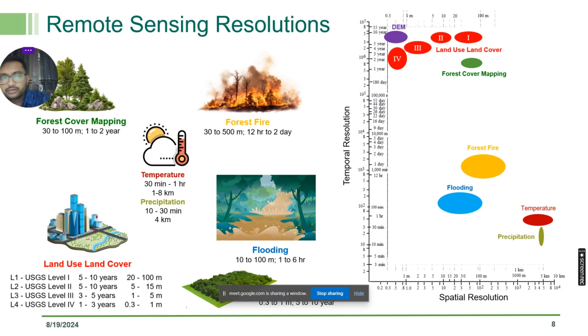Okay, so temperature is a property. We will not get it from the reflectance. When we talk about reflectance, the energy goes to the object, it is reflected and comes back. We will not get any type of temperature information from that. So if you want to measure the temperature of any object, you have to use the right property. There are three different properties: reflection, emission, and scattering. So we have to use emission over here.